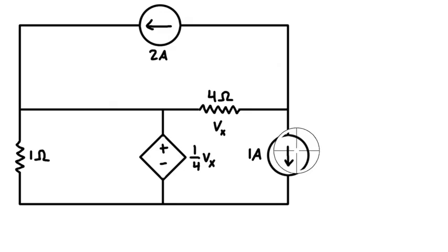And basically at this point you just want to eventually figure out what's going on with the controlling voltage. So we can investigate this junction first. Because we know there's 1 amp of current flowing out, this independent current source just forces 1 amp no matter what to be going through this branch. And same with this one up here, it's forcing 2 amps. So we know that 2 amps are going out this way. And then according to Kirchhoff's current law, what comes in must go out. So we have a total of 3 amps going out, so we have to have a total of 3 amps coming in. Okay, so now we know that there is 3 amps of current in this branch here.